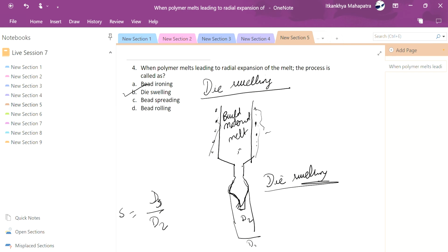So what you will do is, not every time but at least frequently, every 4 to 5 times of printing, you will do the calibration of your print bed. When you calibrate the print bed, we are trying to see whether the nozzle is properly calibrated. If it is not properly calibrated, it will always give bad printing errors. The print surface will never be printed properly.